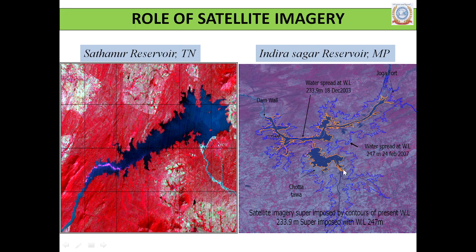These are imaginary lines, but with the advent of satellite data and the image processing toolbox, I could stop my boat. One survey line is around 10 kilometers or so. So it's quite a wide, very large line. You will see water everywhere. Unless you have the line, you'll be wasting a lot of time traveling here. Carrying out one line survey will take about 1 or 2 hours, because your boat is not allowed to move at a speed of more than about 8 kilometers. That's a very high speed. 3 to 4 knots is the IHO recommended survey speed. Okay, so these are all the difficulties in the practical survey.